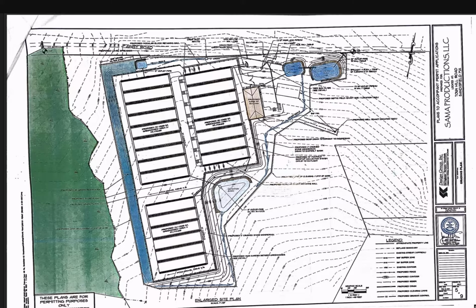Are these greenhouses required to be on the same level, or are they banked up? What I did is each group of greenhouses is on the same level. So I created like 3 steps. There's 3 pods of greenhouses. I labeled them area 1, 2, and 3. And each one is on a different level. And then, because as you increase that change in level, you have driveways that need to slope down or slope up. And I have that around the ends of the greenhouses. And then you have a setback between the 2 pods to allow the 7 feet of elevation change to occur.